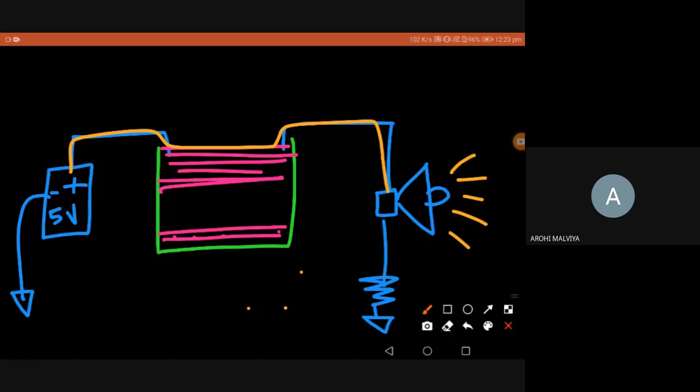But as a designer or engineer, we are always looking towards practicality. Whatever we learn in theory may not be practical many of the times. It is only theoretical. I also learned that water is an insulator, but this is not practical. Whatever water is available around us is a very good conductor. Why? Because there are dissolved salts. Even if you have perfectly distilled laboratory-made water, within a few hours it can become a conductor because atmospheric salts get dissolved in it.